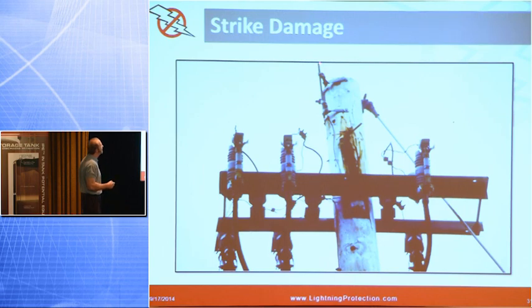Lightning rods don't always ensure collection. Here's a lightning rod on a pole, lightning hit right here, probably a sliver of wood developed that streamer, so even lightning rods aren't 100%. The consensus that I've gotten from the manufacturers, or when I was sitting on the committee before Luke took over, was that there's a debate between scientists about whether it is 90% or 98%, but probably somewhere between 98% effective collecting all strikes and 90% is your conventional lightning protection design.